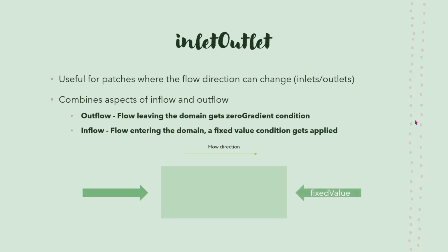Whereas right at the outlet, if you have flow reversal, you may see that a certain fixed value gets applied right there on its own automatically. The user only needs to specify what is the inlet velocity and what is the condition that you've applied here, inlet outlet.